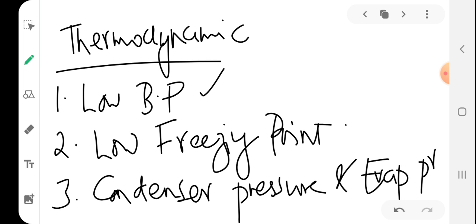It should never happen. If it happens, the heat transfer, the amount of heat being carried, becomes higher. So it won't be easy for the refrigeration system to work. The pressure should be as near to the atmospheric pressure as possible to prevent the leakage of air and moisture. If moisture leaks into the refrigeration system, it will get clogged in the pipeline and all.